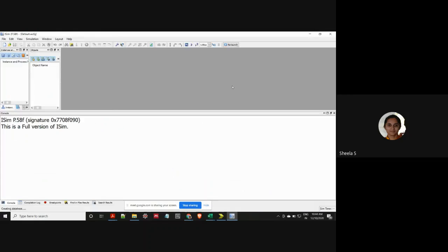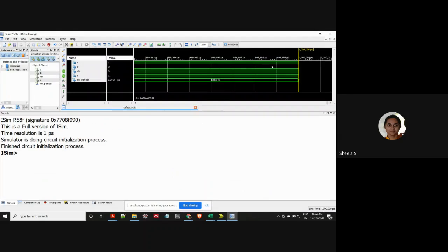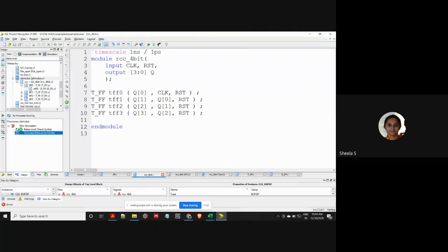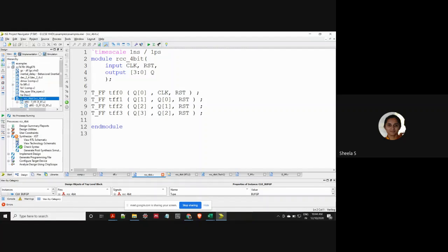Here you can observe that we can get the output even though we do not mention what the output should be for the other reset value. It will not show an error while we are simulating. Now let us consider whether it will be synthesized or not.